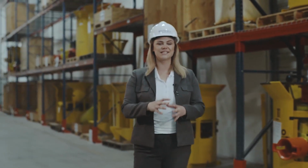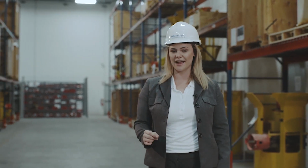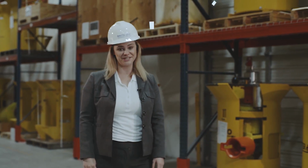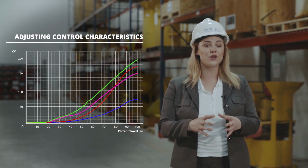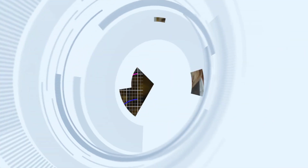The trim cage is compression loaded and constructed as a solid element of tungsten carbide for durability and ease of service. The custom port designs are available to optimize performance depending on the fluid type and gas-oil ratio. This chart demonstrates a few possible flow control curves. However, Masterflow can provide almost any control characteristic to fit the needs.